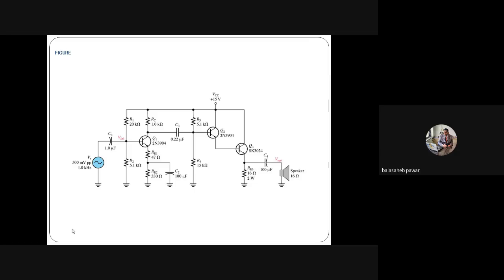Now, it's very simple. Just implement all these components, R1, R2, RC, RE1, RE2 and the transistor. That's all. Power it by 15 volt. Take the DC voltmeter and connect it across collector and emitter, not at the ground. That voltmeter should be connected to the collector with respect to the emitter terminal. Don't connect the negative of that voltmeter to the ground. Otherwise, that voltmeter will measure the voltage drop across RE1, RE2 and across collector to emitter, so it will show the combined voltage drop.